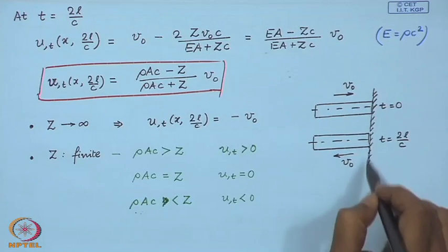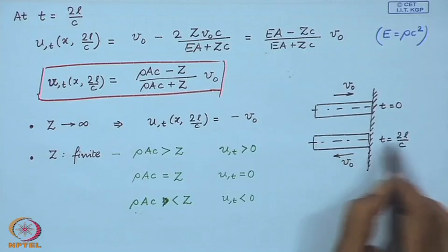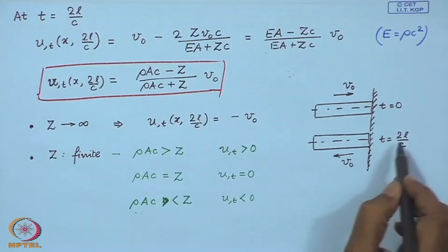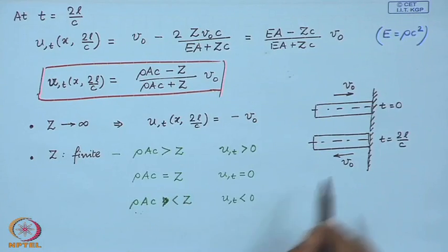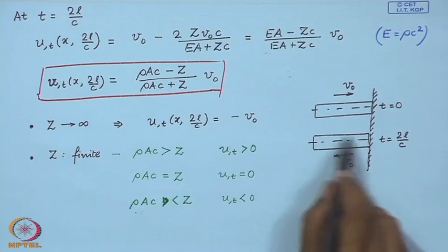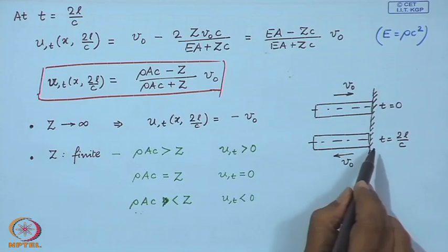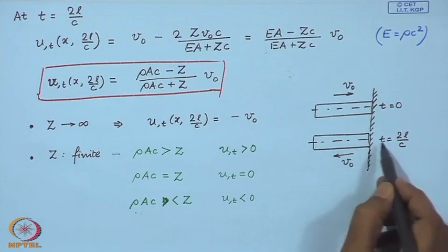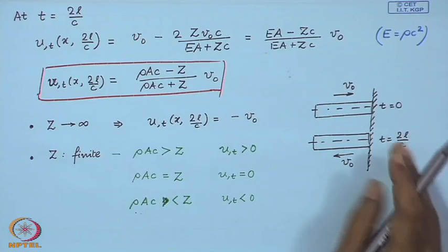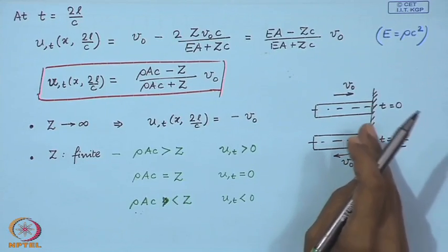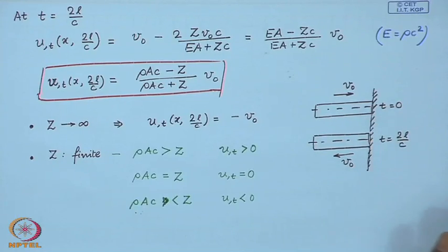It is going to lose the energy in this wall or the semi infinite bar as we have considered. Because this impedance is now finite, some part of the energy of this finite bar which is incident here is going to go into this wall or the obstacle. So, some part of the energy is going to be radiated into this obstacle.